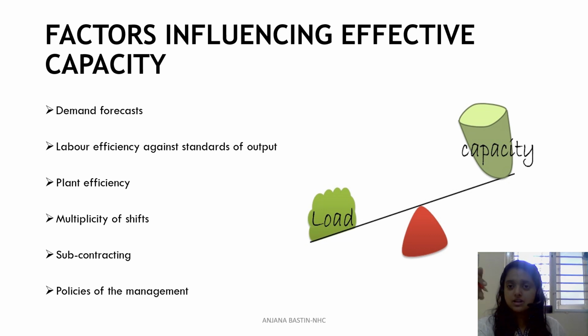Now the number of hours in a month for this machine to make the lead would be around 700 hours, 700 machine hours. So in order to consider the efficiency, we divide 700 by 80%. We get the answer as 875 hours. So even this one cannot maintain the standard of 700 hours. They would need 875 hours. Okay.